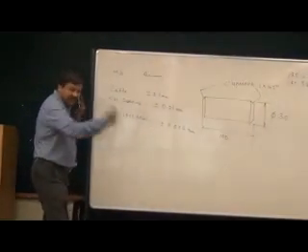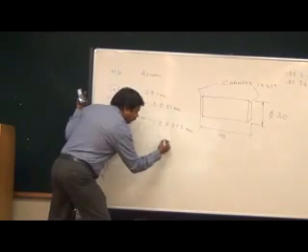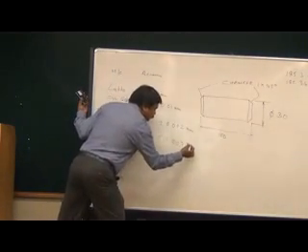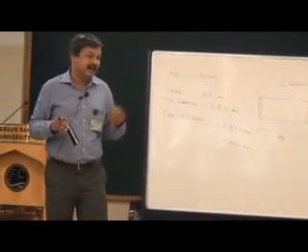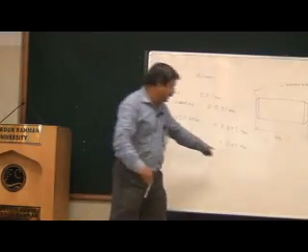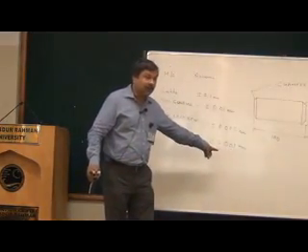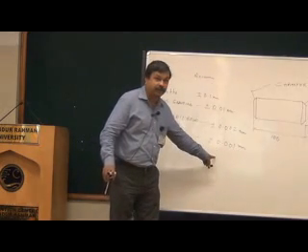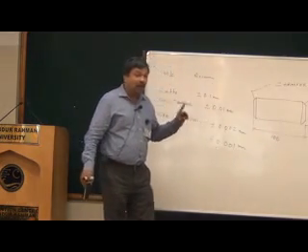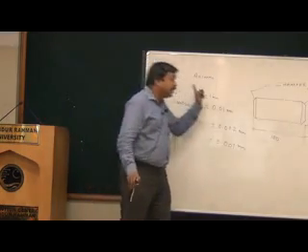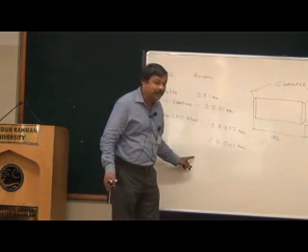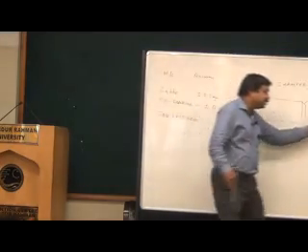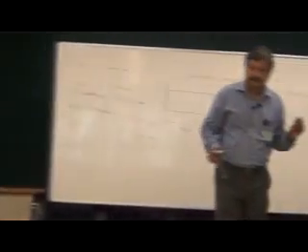Probably, if I do some honing or lapping, some other process, I can get an accuracy of plus or minus 1 micron. There is some other process called cylindrical honing or cylindrical lapping, in which case I can get an accuracy of 0.01 mm. This is 1 micron accuracy. Now the basic issue is in which machine to manufacture. That I will know only if the tolerance band is specified.